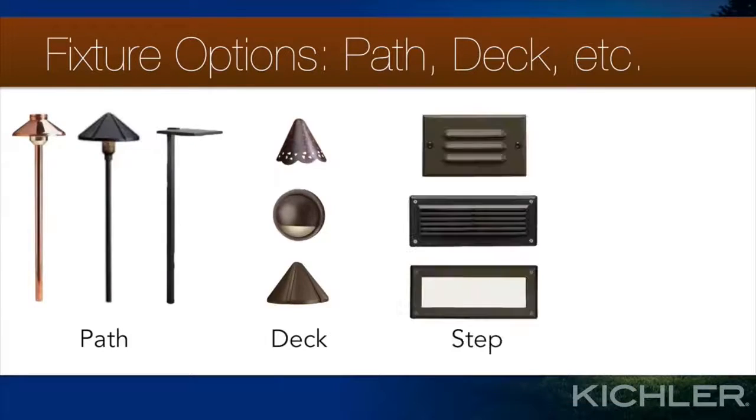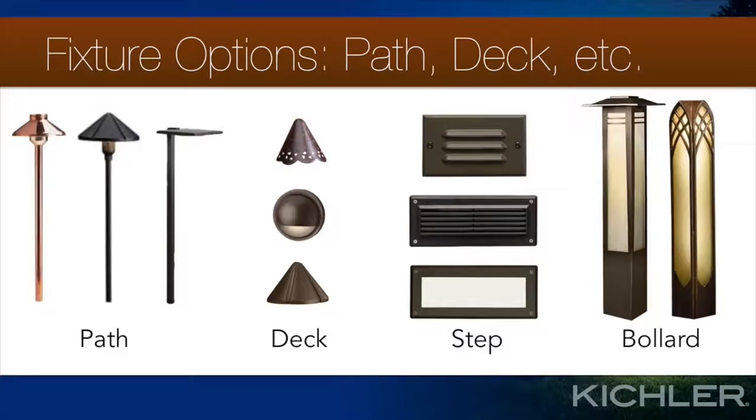Path lights, deck lights, step lights, and bollards come in a variety of styles that can be customized to your customer's preference. A word of caution: don't give your customer the catalog and tell them to choose. Most distributors carry the most popular styles in stock and have to special order the rest. It's usually best to show a customer 2 styles that the distributor stocks and allow them to choose between the 2. They feel like they've contributed to the style of their installation, and you won't have to worry about the headache of special ordering fixtures. For the customer with discerning taste, a wider variety might be appealing. Just be sure to let them know up front about longer lead times and potentially higher costs, especially if they want an unusual fixture installed, say, tomorrow.